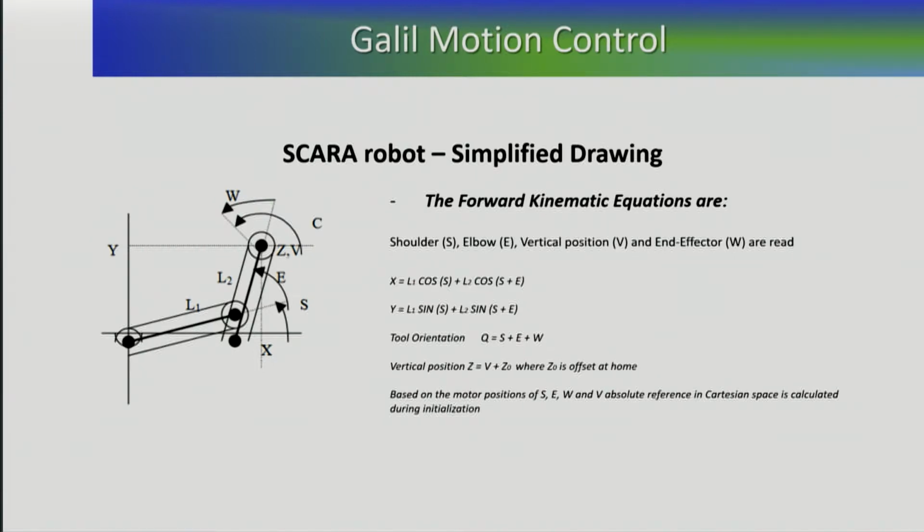So when you power up the system, you can do initialization one of two ways. You can say, I'm going to do homing of each axis joint and set a known reference point. You could do that. However, in many cases, you do not have the capability of moving the robot upon power up because there may be obstacles, or the potential risk of damaging the mechanics.